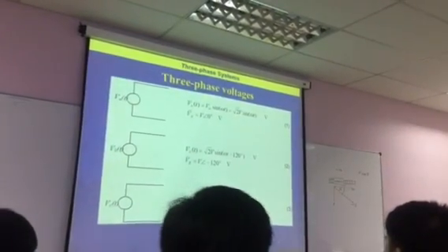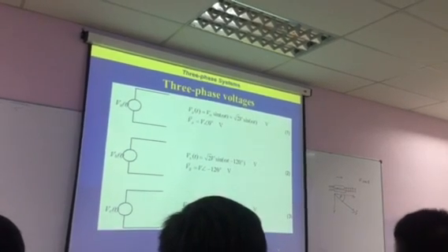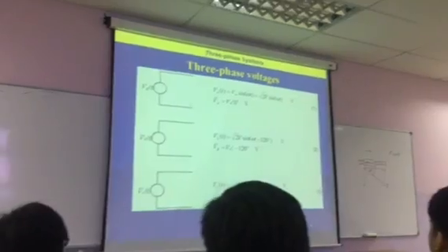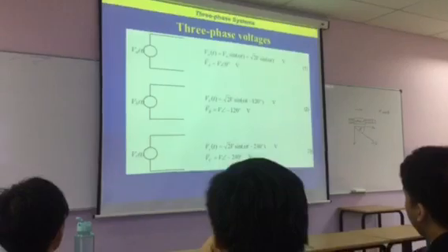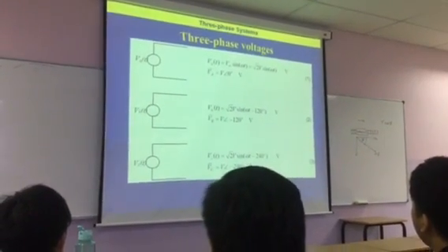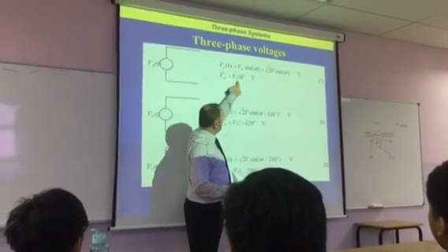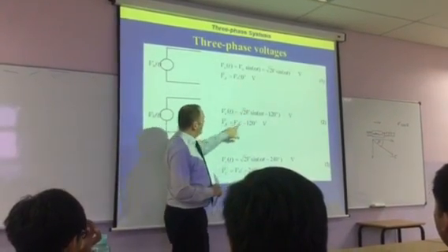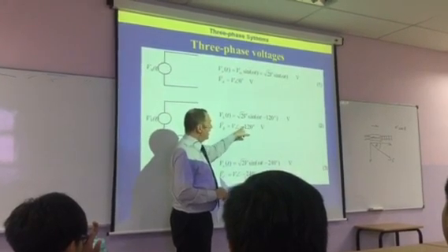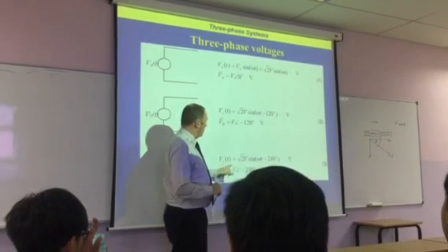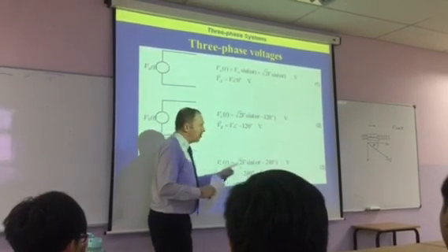And then if we work out the phases, the instantaneous value is the peak value times sine omega t, or the RMS value there. The notation we tend to use is that VA is delayed by a factor of 0 degrees. VB, because it's lagging, is minus 120, and VC, a further 120, so it's lagging 240.